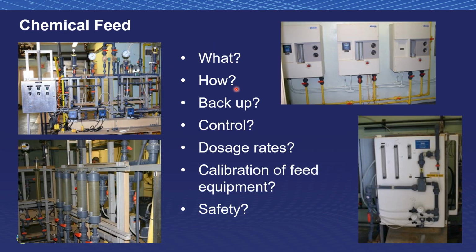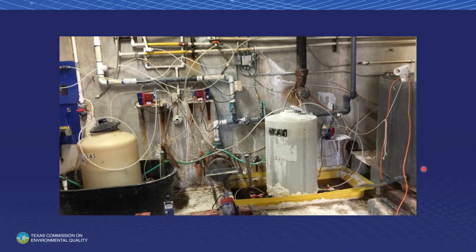What chemicals are being fed? How are they being fed? How are they being generated? Is there a backup chemical feed system? What's the control algorithm look like? What are the dosage rates that you expect? So these are all good installations. This one, not so much so.